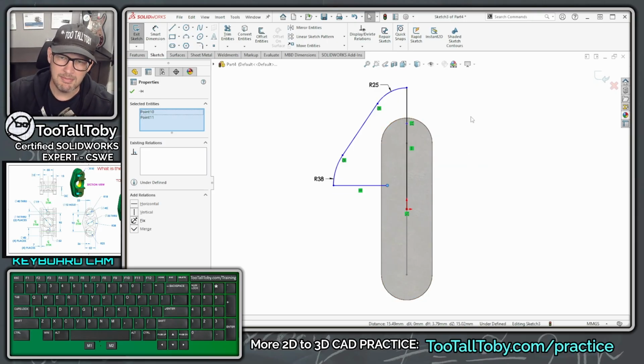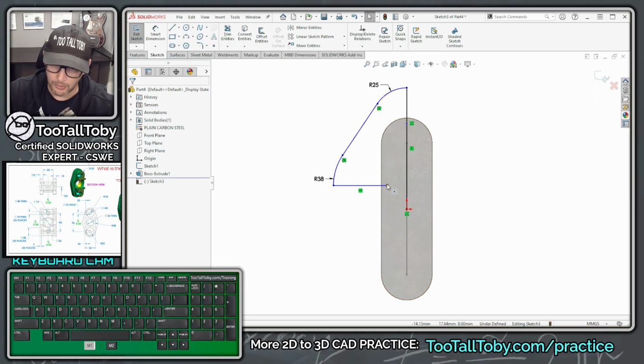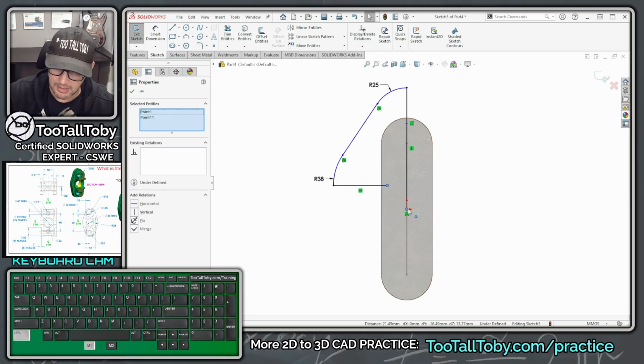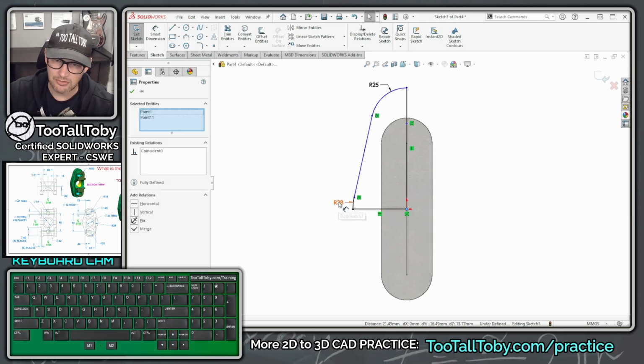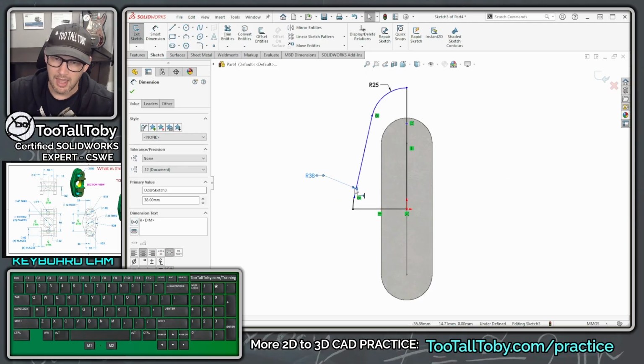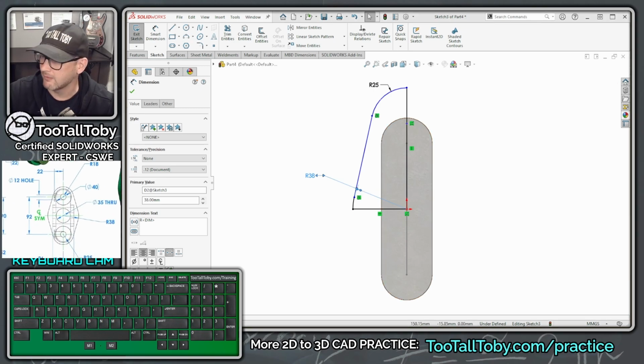And then you can do the same thing, click in the background, click this point, hold control, pick this point here, let go of control, and once again, you can do a merge points, and that takes the center of this 38 arc and puts it exactly here at the origin, and we can see that being called out here in this view. So the center of that 38 arc is directly on the origin. So another good reason that we chose that location as our origin.